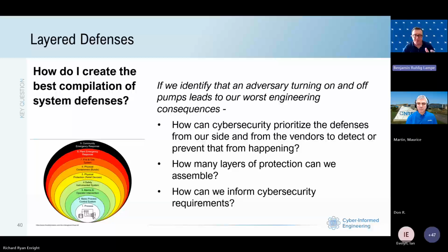so what CIE offers in this, and as we relate to the pump house example, when we introduce the time delay relay with the security and the monitoring we apply to the network and the PLC and the tunneling to the cloud provider that is able to issue commands to the pump, you start to track all those layers that contribute to the overall protection, in this case of the pump and its ability to maintain pressure, but from a consequence side, its ability to prevent the overcycling of the pump, whether for thermal damage or for water hammer effects in the larger system.